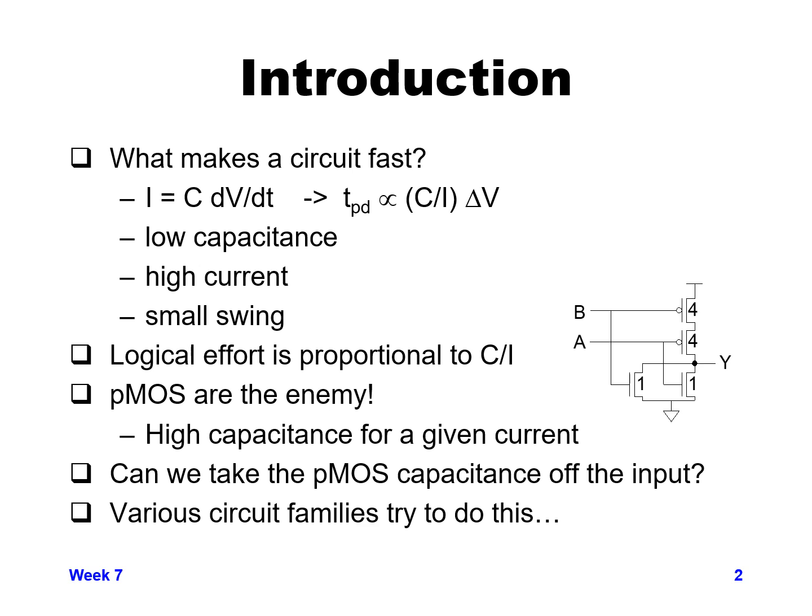So next thing to note is that our logical effort is proportional to the C over I term. And when we look at our capacitance, keep in mind, here is shown a two-input NOR gate. The input capacitance C is going to be the sum of the PMOS device plus the NMOS device size. Since we pretty much always need the PMOS to be a lot larger than the NMOS, especially for this NOR gate, for example, the PMOS is 4 times the size of the NMOS. So the PMOS is a critical thing to try and reduce if you can.